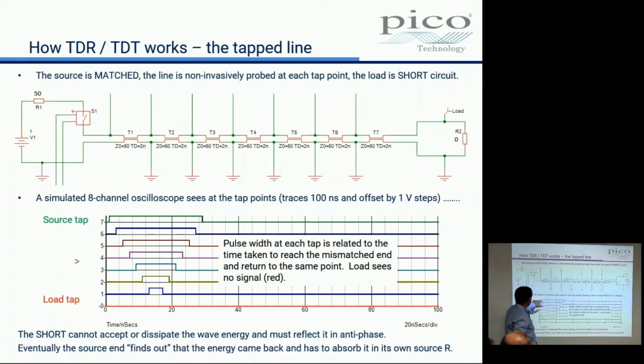So actually we generated, at this point here, a pulse. And the pulse widths along the cable were shorter and shorter according to how far they were from the short circuit. Okay, so strange things happen in cables that have a length that is relevant to our measurement.